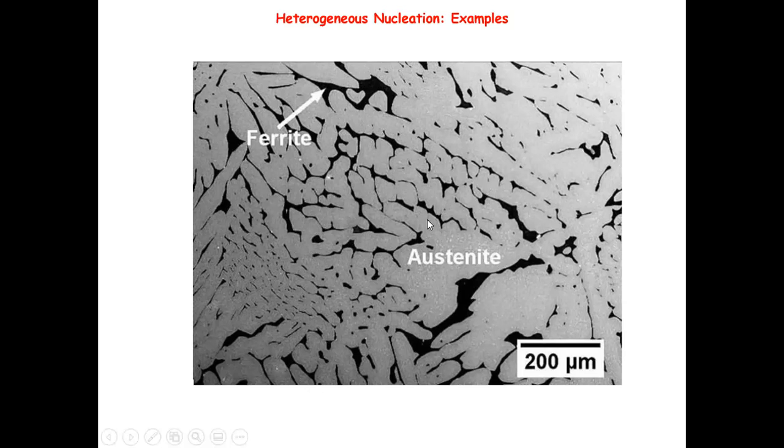And what you can clearly see here is that, although we didn't show the grain structures for the austenite, it's quite clear from these plots that most of the ferrite is actually on the grain boundary. What you see here is not the initial stage of nucleation. It's already at room temperature. So what you see is a large amount of ferrite phase, which all grows along the grain boundary. From this image, you can trace what the grains look like without using EBSD, because all the ferrite phase forms on the grain boundary, maybe at a triple point, but grows along the grain boundary.